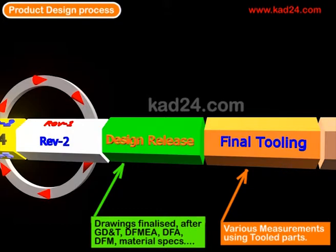One has to confirm the GD&T, DFMEA, DFA, DFM, and the material specifications, and then release it for final tooling, which costs a lot of money. The real investment is in the final tooling. After the tool parts arrive, various measurements should be done on the tool parts.